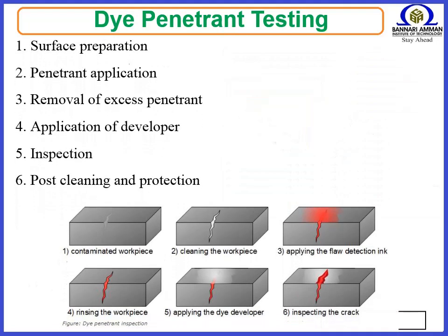The basic principle of liquid penetrant testing is that when a very low viscosity, highly fluid liquid, the penetrant, is applied to the surface of a part, it will penetrate into fissures and voids open to the surface. Once the excess penetrant is removed, the penetrant trapped in those voids will flow back out, creating an indication. Penetrant testing can be performed on magnetic and non-magnetic materials, but does not work well on porous materials.